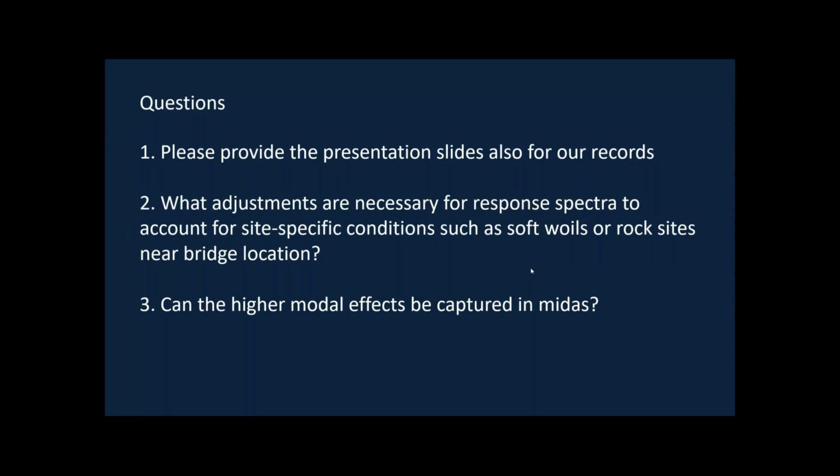Then what adjustments are necessary for response spectra to account for site-specific conditions such as soft soils or rock sites near a bridge location? So when we evaluate the response spectra, or try to specify the demand response spectrum that we need to consider, the soil categorization is basically done on the basis of whether it's a soft soil, rock soil, etc.